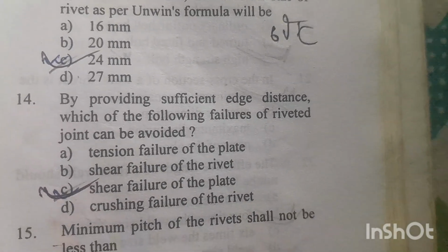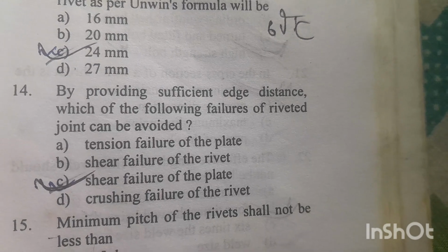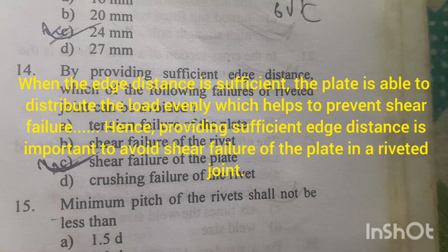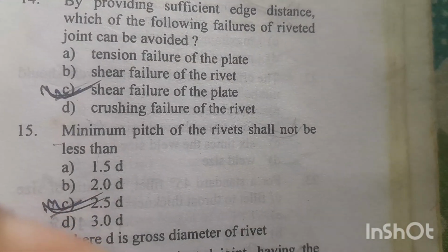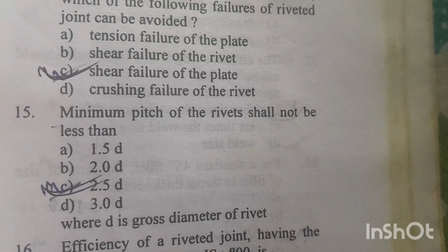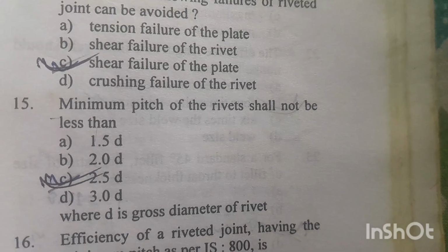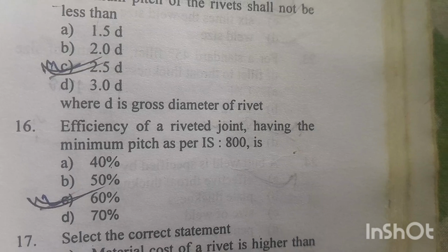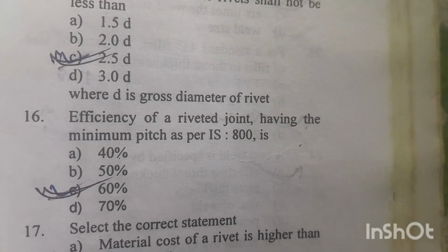Question number 14. By providing sufficient edge distance, which of the following failures of riveted joint can be avoided? Shear failure of the plate. Option C is right answer. Question number 15. Minimum pitch of the rivet shall not be less than 2.5 d. Option C is right answer, where d is the gross diameter of the rivet. Question number 16. Efficiency of a riveted joint having the minimum pitch as per IS 800 is 60%. Option C is right answer.